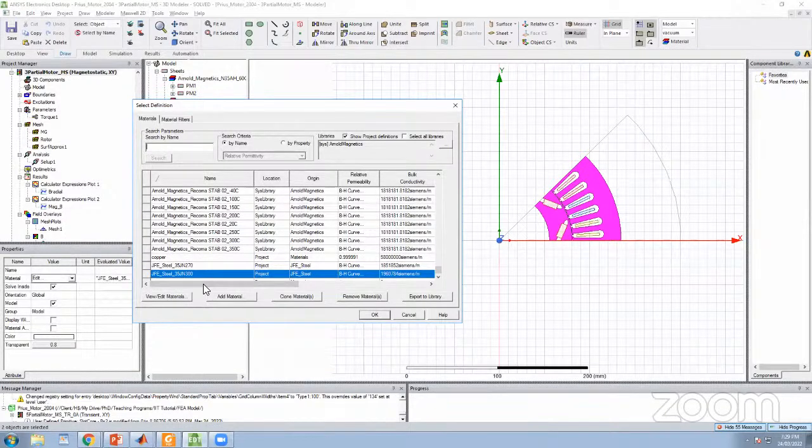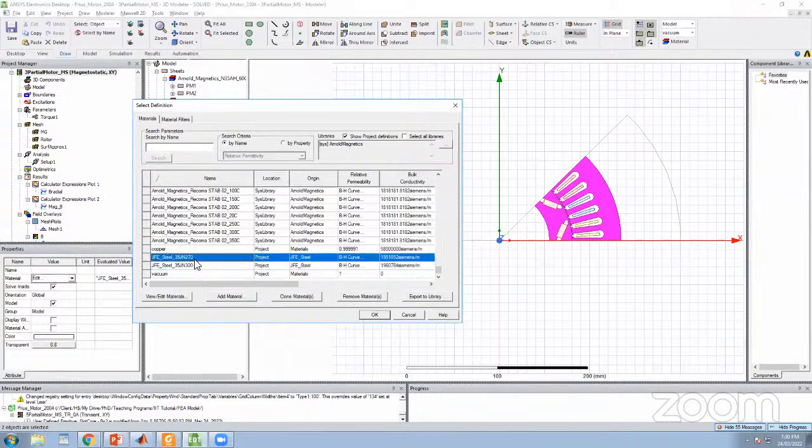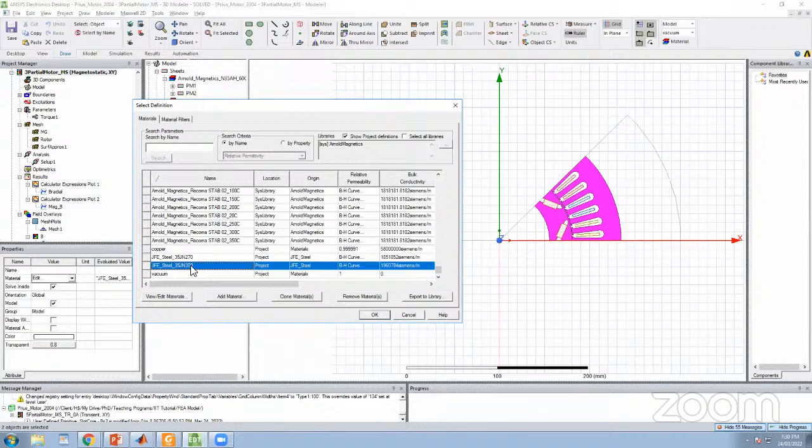The last 3 digits, you can see this 270 or 300, represent the loss property of the material. The higher this number is, the more loss will be produced when you use this material. But also, if you want to use a material with a lower loss property, it will be more expensive. So in this case, we select this one.